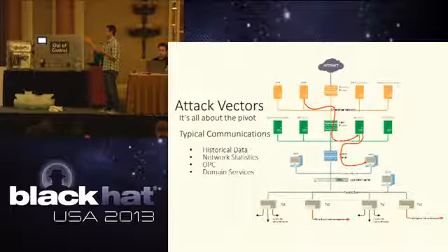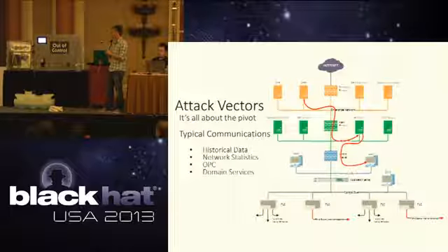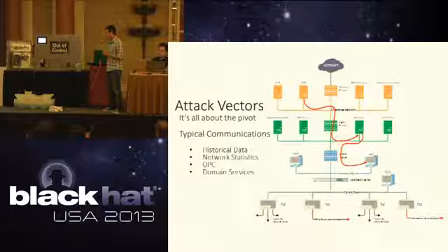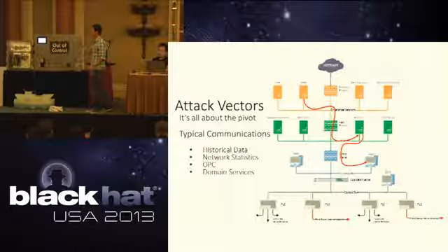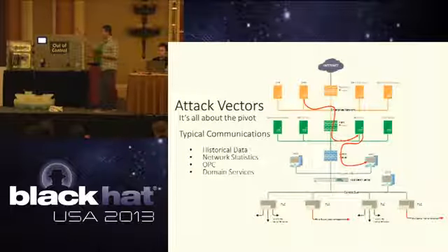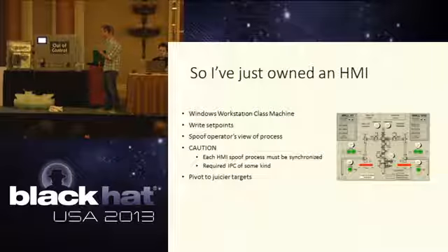One would be just regular old historical data, but what we're going to mention quickly here is OPC. If any of you have heard of OPC, it stands for OLE for process control, or object linking and embedding for process control. Essentially, it rides on top of DCOM, which many of you might know is a deprecated protocol used by Microsoft, but it's used everywhere in the process control industry. The implication is that because it uses DCOM, you have to open up a ton of ports on your firewall to allow that data to traverse it, because it picks a port at random to assign to that OPC communication. So even though it's deprecated by Microsoft, you see it everywhere in the process control industry.